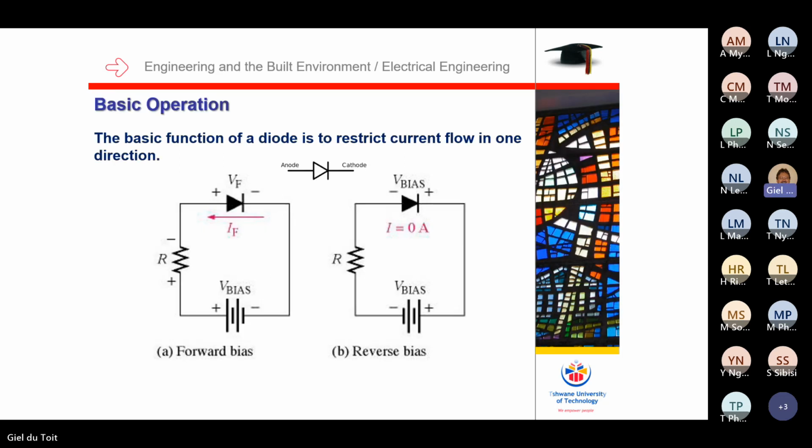I've shown you the forward bias diode circuit, and this is how it looks. The reverse bias is when the current goes in this direction, reverse biasing this diode. So we know that only a zener diode works reverse bias, a varactor diode, a pin diode, and what else is it? Only those special diodes really work in reverse biasing. Oh, and the optical diode also works with reverse biasing.